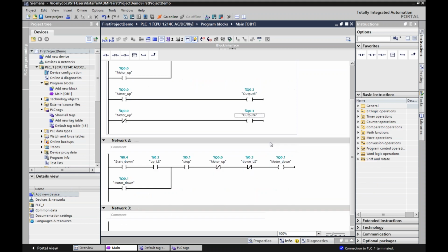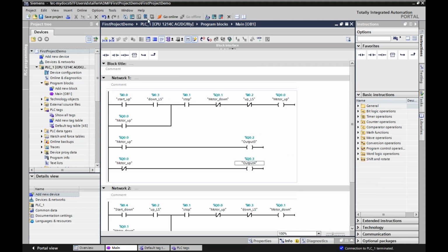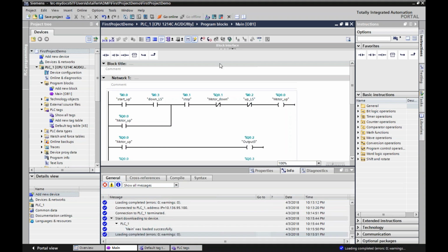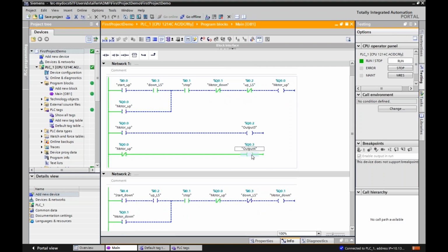So all I did was just add another little rung. And now go live. Let me hide this. So right now I have output 4 because motor up is not running. And now if I hit start, it's running, and there's not running. Running. I'm not doing a sequence. I just want to show you that just because I'm controlling it up here, I can use those same bits to affect statuses, and these could be pilot lights or another process. It doesn't quite matter.